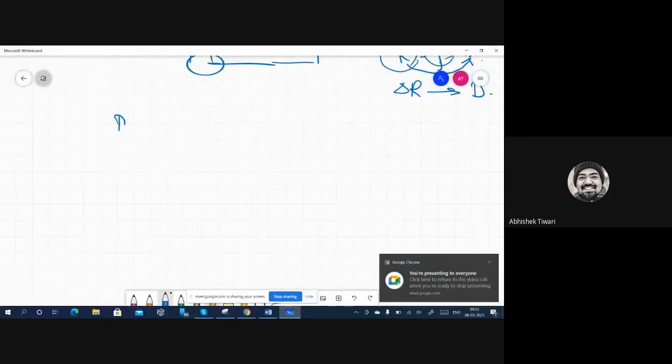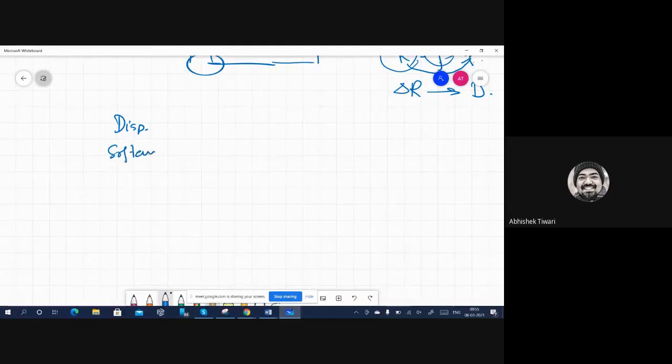So the things which we have to understand are displacement and the softening, and what else was there? Degradation and displacement at failure. So displacement is the type which Abaqus is asking for.